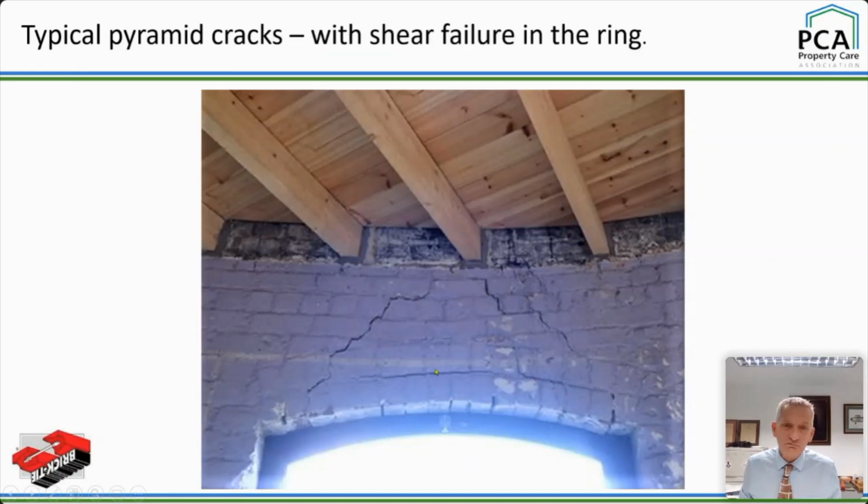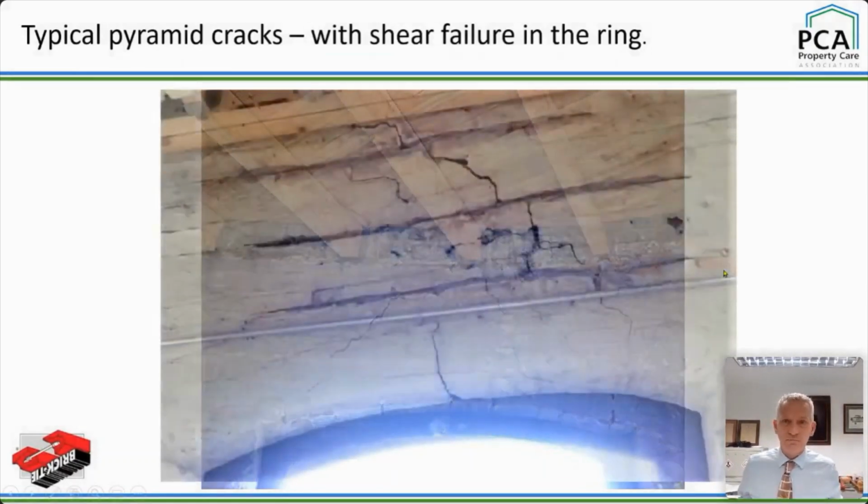Look carefully and you'll see these cracks running in the rings. That's the shear stresses generated by arch failure. All right, well, it's generated in all arches. But if we just hold our hands like that and then imagine if we want to make that shallower or deeper, your hands have to slide. All right, they have to slide up and down. Masonry doesn't do that, it rips. Okay, so in a basic way, that's the effect of shear cracking.